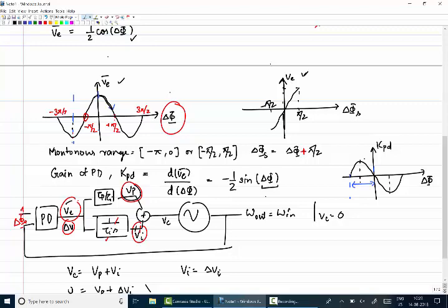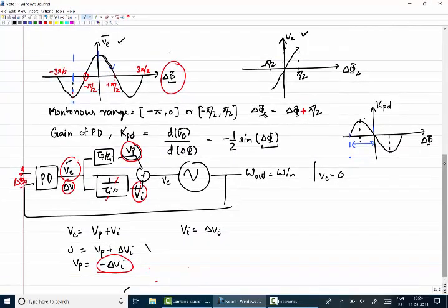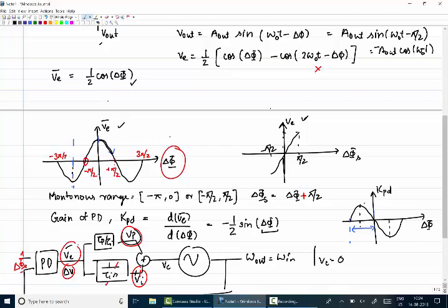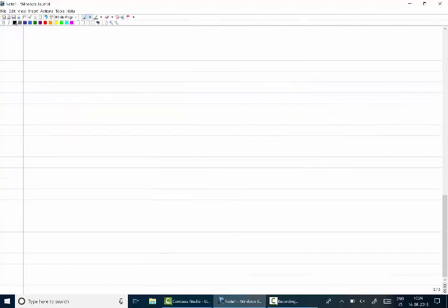Okay. So whenever we write a linear gain of the phase error detector and we are using this particular mixer based phase error detector, we should be aware that whatever value of Kpd we are using is valid in a very, very small range. Okay. Now there is another analog phase error detector which is sampling based, or sampler phase detector. Okay, what does it do?